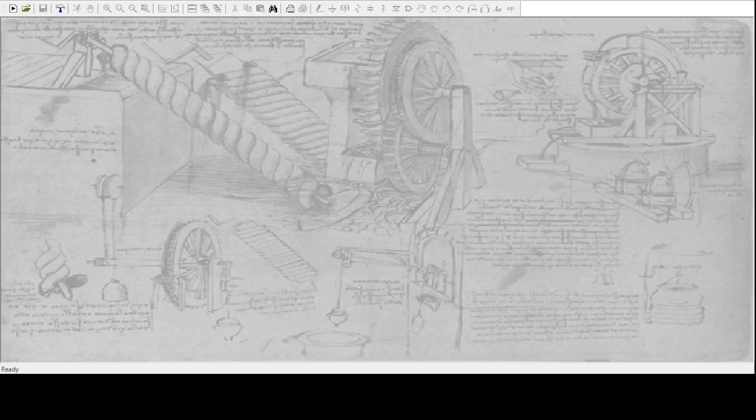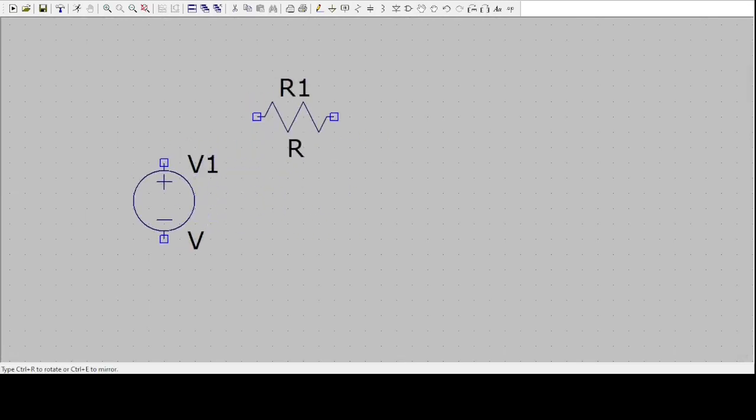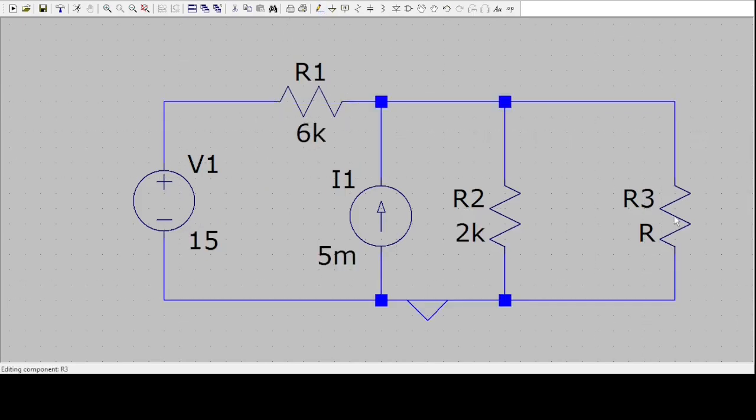The same thing can be verified in LTspice. So let us create the schematic in LTspice. Open a new file. Let there be a voltage source and some resistances. So this is our given circuit. Let's connect the terminals, and the load resistance can vary from 0 to 5. Let's assume this is 2 kilo ohm. We're calculating for a 2 kilo ohm load.